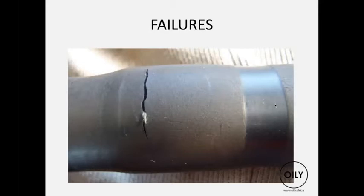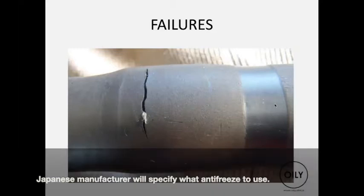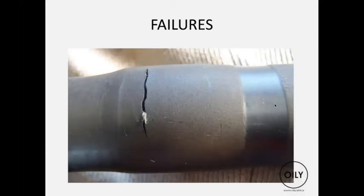I think it was a Japanese-built vehicle, and they used a European-spec'd antifreeze, and the antifreeze was not compatible with the rubber that they used for that hose in Japan, and it softened the hose and it burst. The Japanese manufacturer would have specified what that antifreeze needs to be. Yes, and you'll see just now there's a difference between antifreezes coming from different regions.